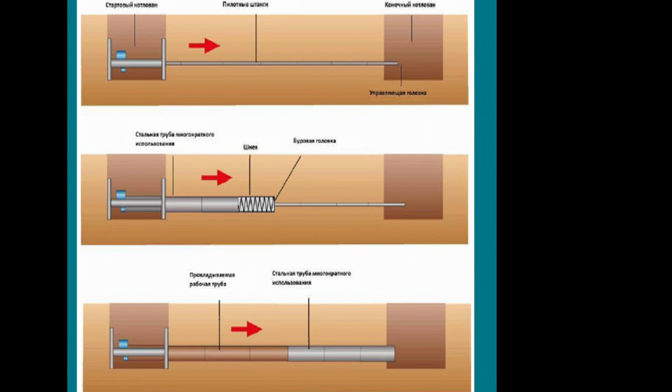A powerful jacking station with a pipe ramming mechanism placed on it is mounted in the starting ditch. On the first stage, the preparation of the starting and adaptive ditches is accomplished. On the second stage, the descent and installation of the auger rig is done into a ditch. On the third stage, the pipe laying is carried out, controlled by laser. On the final stage, the auger is driven into the adaptive ditch and then it is pulled out in the reverse order after the rig and the augers are extracted from the starting ditch.